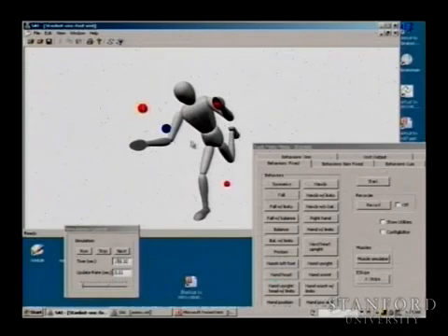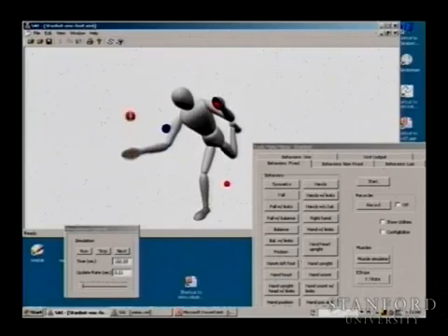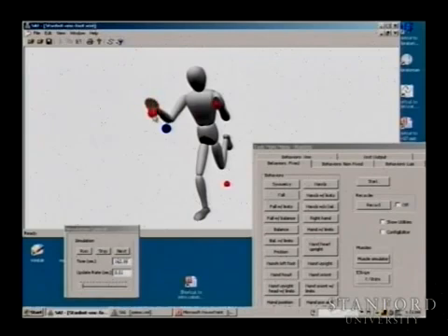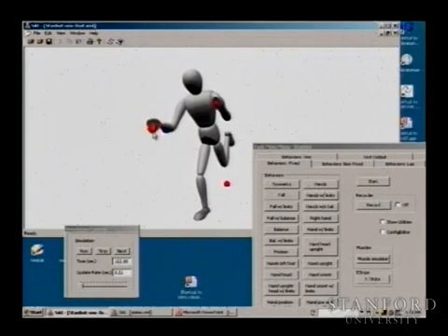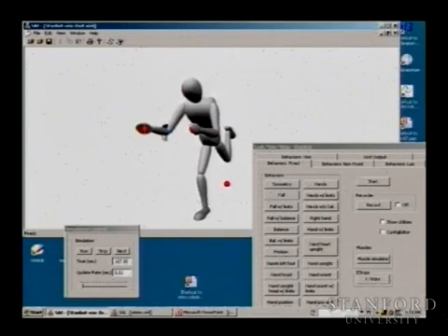So there are other things that need to be taken into account. And what we are doing is we are also applying other potential energies to the rest of the body to balance. So when we apply this force, you see it's just following, like a magnet. It's following this configuration. There is no computation of the joint positions. Simply we are applying these attractive forces to the goal. You can apply it here, apply it there, or apply it to both.